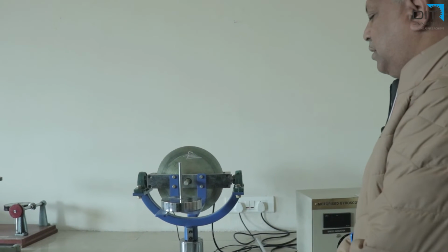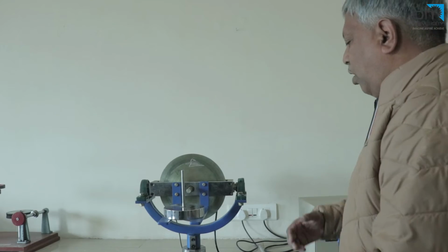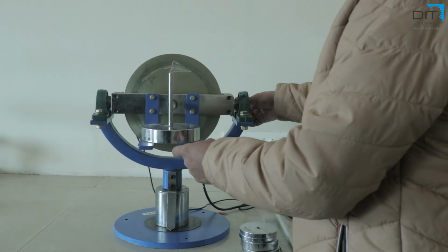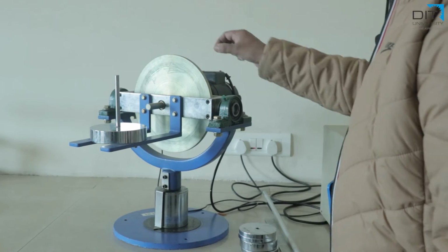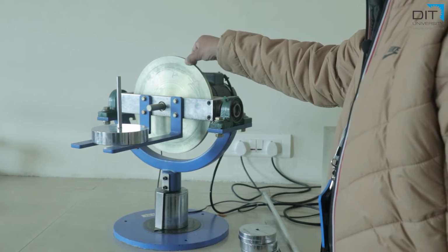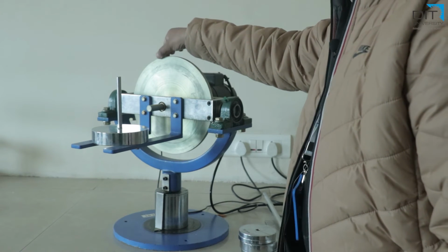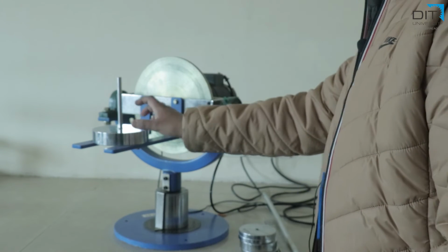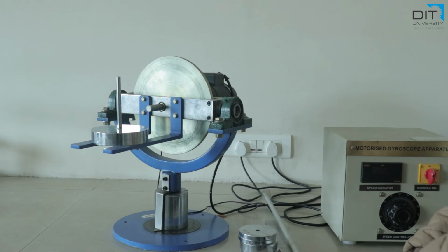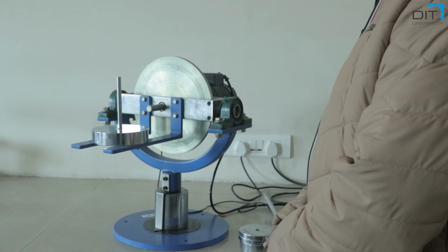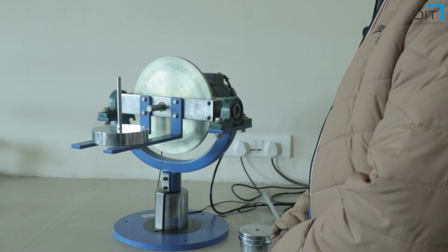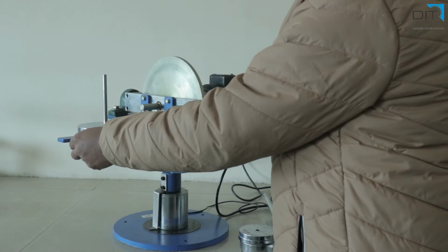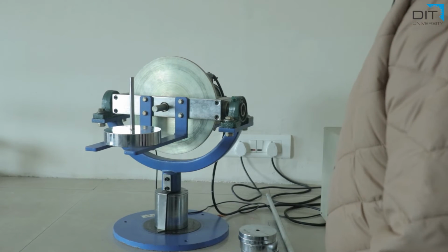It has been observed the speed of spin... This is a precession. The speed of precession basically depends upon the moment of inertia of this disc, number one, speed of spin of the disc, number two, and the torque we are giving by putting a mass over here. Let me again tell you, the gyroscopic effect, which is the rotation of the setup about the vertical axis, will depend upon three parameters.